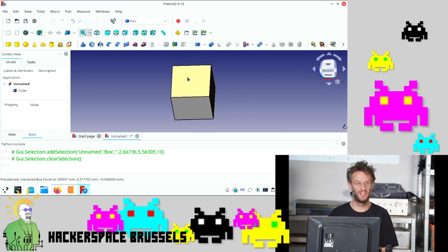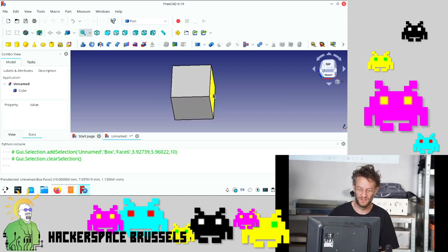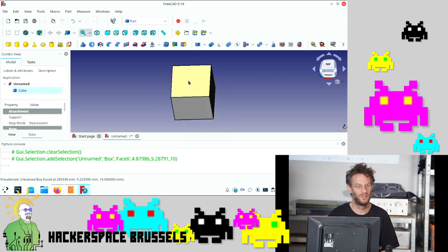So this cube that I created here has a geometry definition that has no visuals, and then it has a visual part. That's how it appears on the screen. That means these faces are rendered as gray rectangles, and then you have these lines, etc. I can inspect things. That's one of the first uses we make of the Python console. For example, am I sure this is a cube? I could have imported this object and I'm not sure what's inside. Maybe instead of one line, it has two lines very close to each other, and then it would have 9 vertices instead of 8.